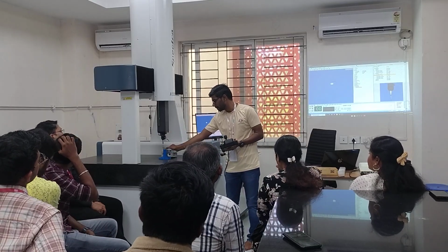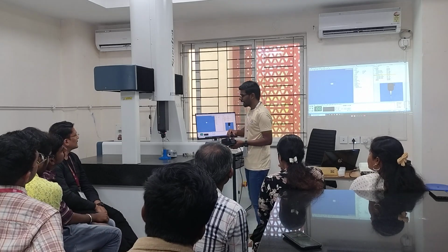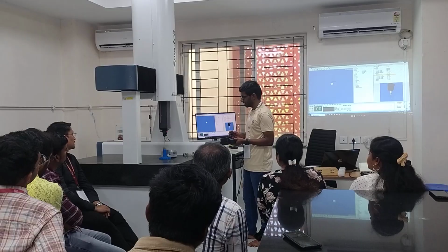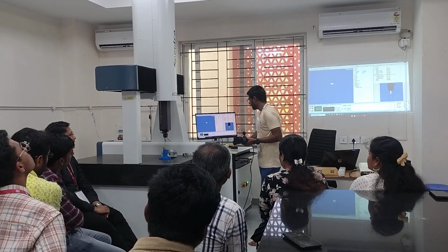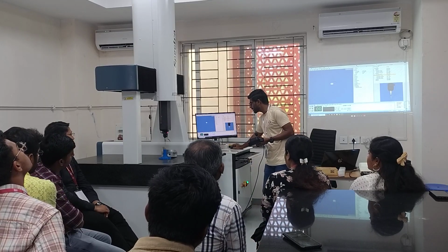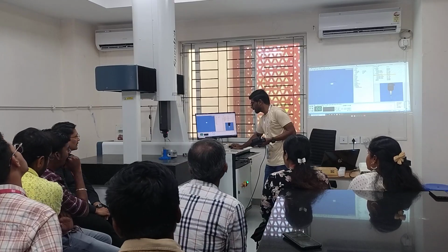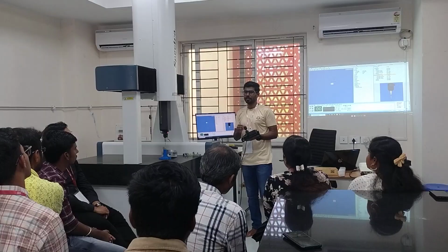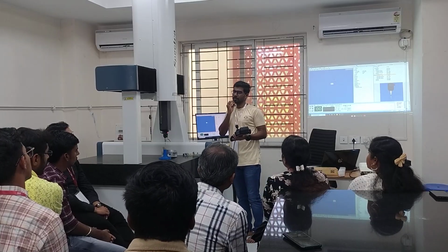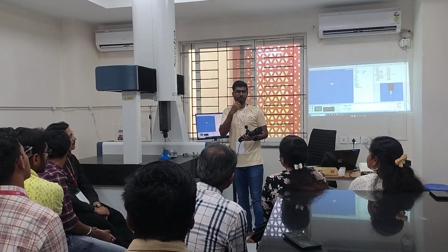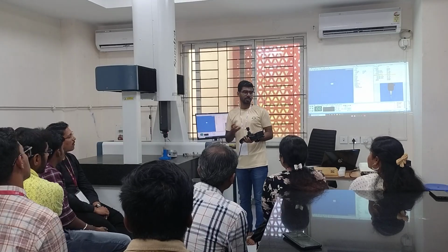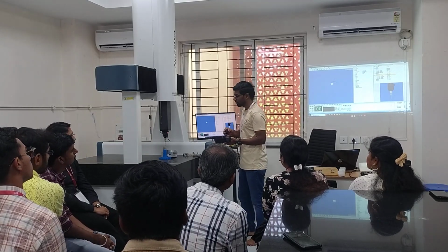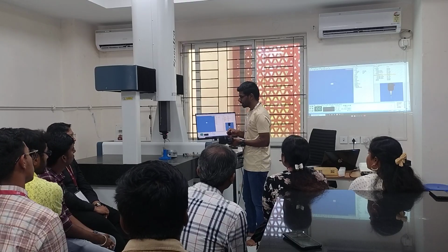I measure the distance between them, and then I will not do the circularity now. Okay, let me do the circularity also so that we can compare. So plane is done. Now what I have to measure? Let me measure circle. So I'll click on circle. For circle, how many points are required to trace a circle? 3. Minimum number of points? 3. Because 2 will give you just a line. 3 will give you a circle.